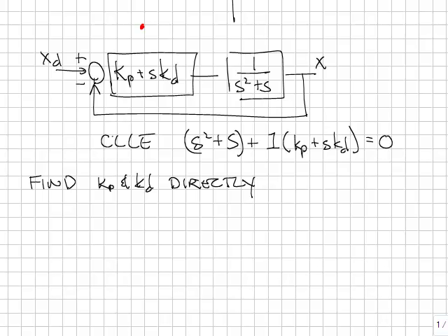In a second order system, recall that given a PD controller, you can place the poles anywhere, which means any second order characteristic equation is valid. If this was a third order plant, I would have to pick something, probably by looking at the root locus, finding something that's possible to do with Kp and Kd, and then solving for the coefficients directly.